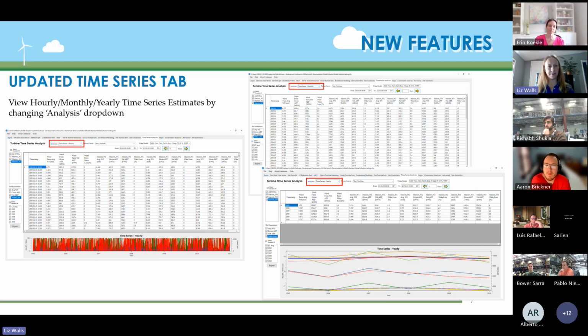Now when you go to the time series tab, there is a top panel and a bottom panel. We have the tabulated data in the table above and then a plot on the bottom. You can move the windows up and down to take a closer look at either the table or the plot. There are different options of ways to look at the data. There is a drop-down menu at the top here named Analysis. By default, it'll be selected as Time Series Hourly. So you can take a look at all the hourly estimates, average wind speed, gross and net production, as well as wake loss, again, on an hourly basis.